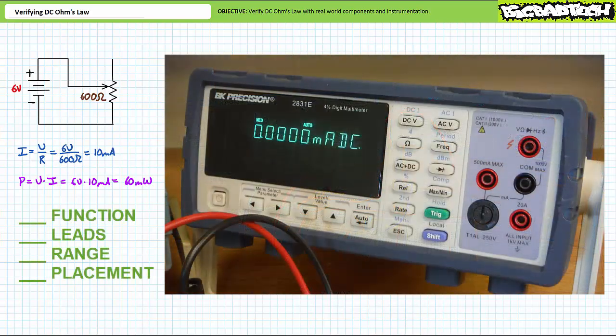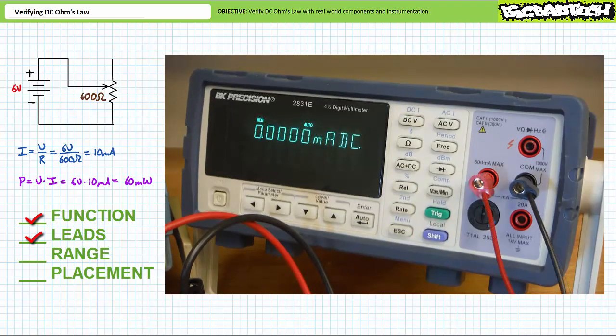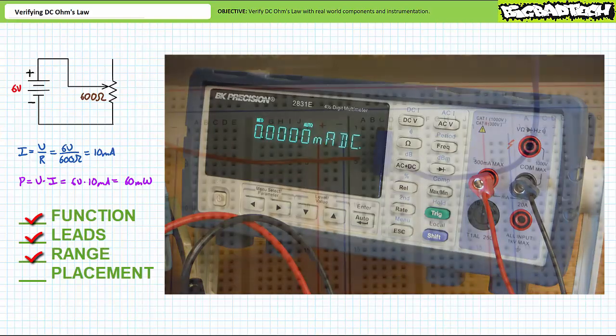Let's now put the DMM in DC ammeter mode to measure current through this system. Let's use the checklist to do so. Function, leads, range, placement. Function. Choose the DC ammeter function. Leads. Black lead into the black common hole. Red lead into the low current input hole marked with a milliampere symbol above it. Of note, an ammeter uses different lead placement than a voltmeter. Range. Don't worry about it.